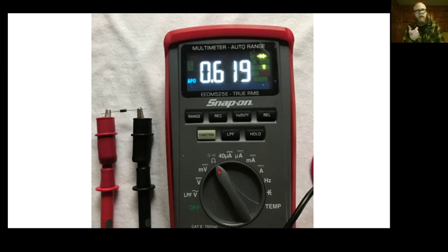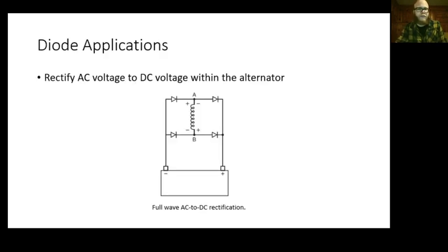and the only way I'm going to get it to allow me to flow in that reverse bias on a normal diode is to melt the diode and ruin it. So at that point, it's either going to be open, or if I get lucky, it'll melt and fuse itself together, and then I'll be able to pass current through it both ways, just like it was a wire.